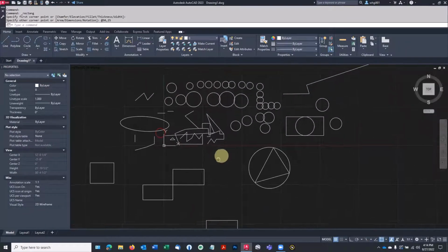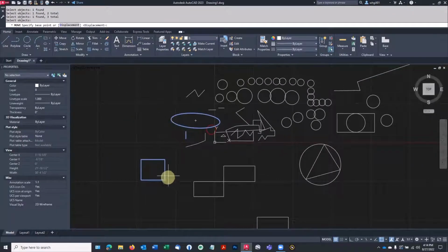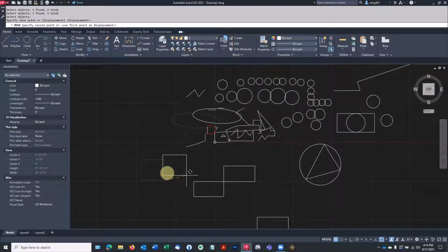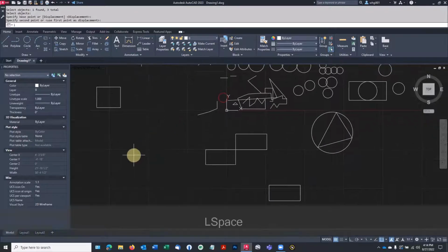The modify tools, let's do move. So this, you select the command, pick the object or objects you want to move, hit enter to say I'm done selecting them. Now it says specify the base point, which is where you're starting from, let's say from here. I want to move them all over to here, or to here, just to get them out of the way. And you can use the object snaps to move them a specific distance, for instance.